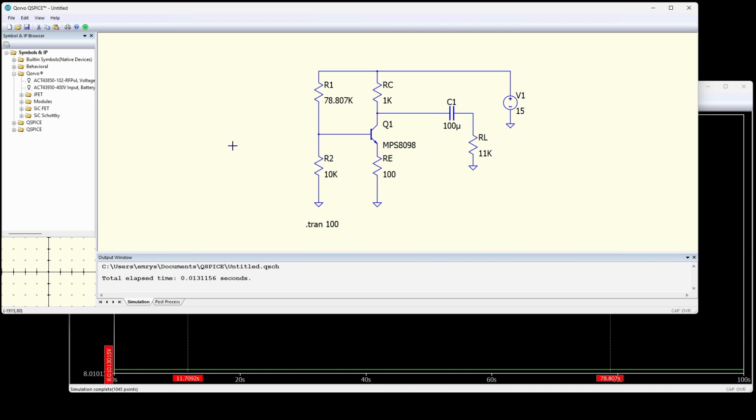So now that I have my circuit set up, I have configured everything the way it's supposed to be. I'm going to go ahead and add in my input voltage. And this is going to be set up for an AC analysis. So I'm going to say AC equals 1. You have to give it a value of 1. This is a common thing in simulators, and if you're used to Spice, it's something you just kind of pick up along the way, but AC equals 1 is required to do an AC analysis, and if you don't have 1, then you won't get the correct gain numbers at the other end of your circuit whenever you test.